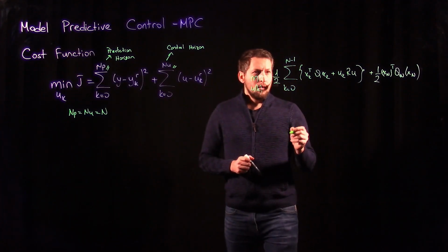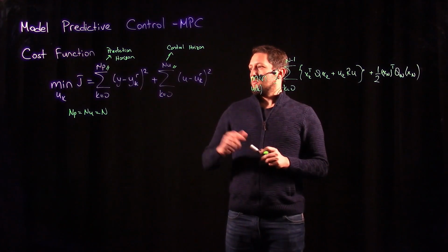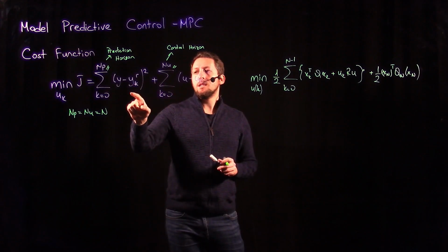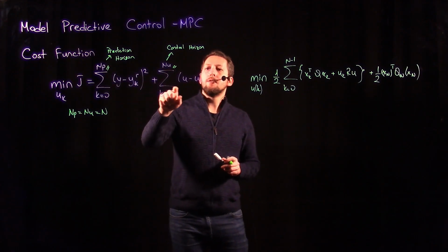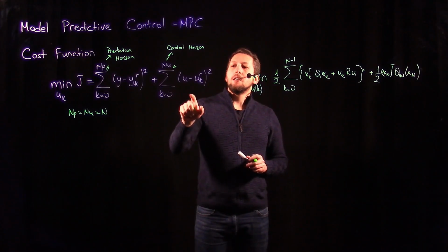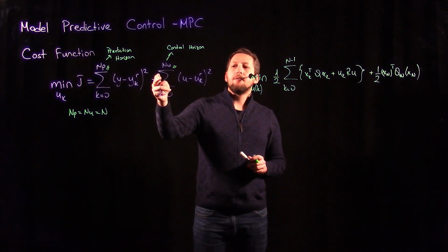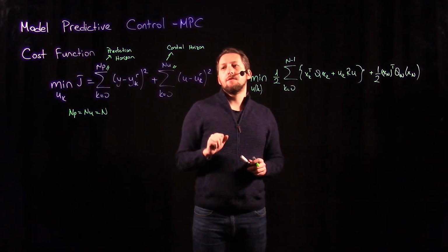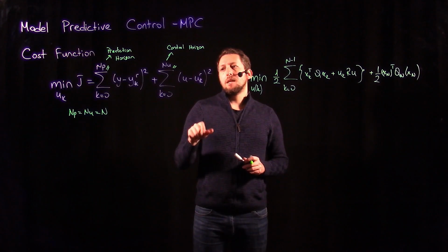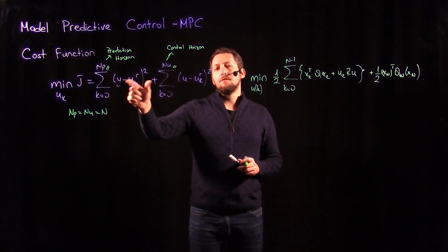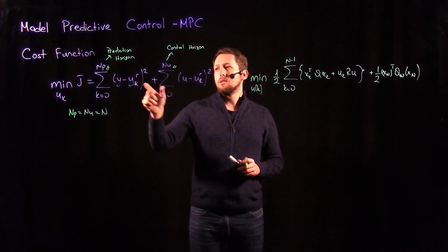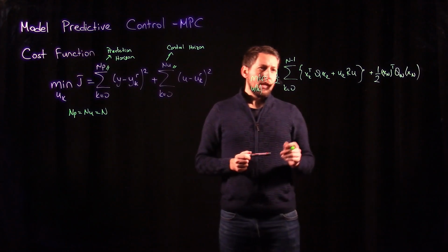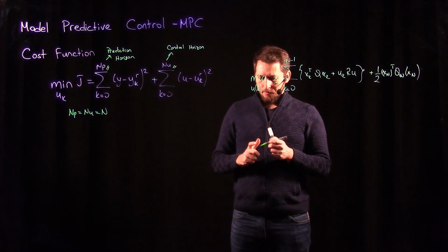Maybe I didn't mention it here: what we don't have in this one is weighting. For example, if the error on the inputs is more important to me, then I can add a weighting factor before each of the specific input variables, so that I can make them more prioritized. Or if the output of my system is more important, then I can also weight that specific output or all outputs. This is basically what we are doing here.